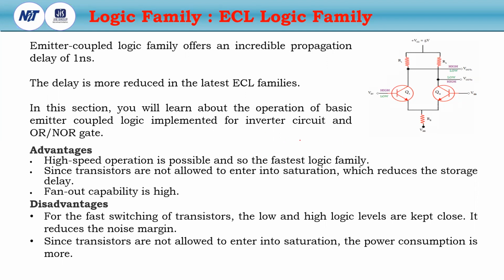In this section, we will describe the OR and NOR gate in ECL logic. There are some advantages: high speed operation, reduced propagation delay, and very high fan out capability. There are also disadvantages: the low and high logic levels are kept close, so it reduces the noise margin.